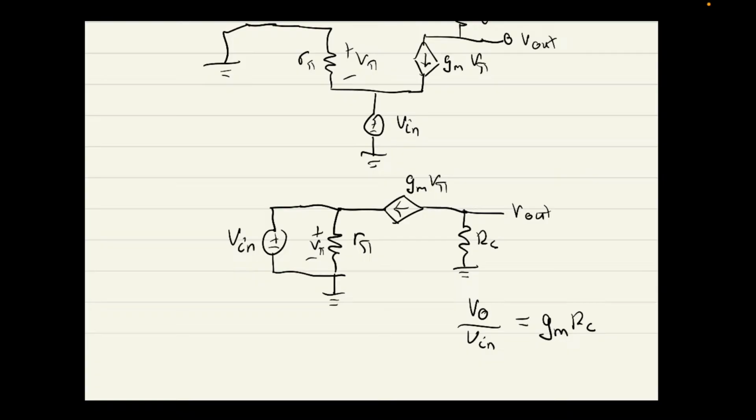So if you had, which we might see in the crash course in a different question or in the exam, a 2-stage amplifier, the small signal model for that, like I said before, is pretty big. But you can turn it into 2 stages. You can just find the gain for the first amplifier using the known equations and the input resistance of the second amplifier. Then you find the gain of the second amplifier and multiply those together. You don't need to go into a small signal model, which will probably save you a lot of time in the exam. And that's why that doc's been made.